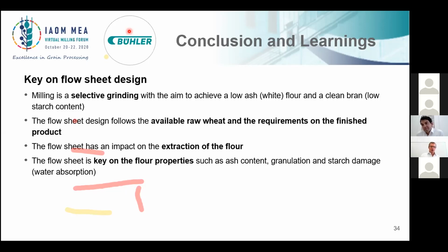There is more a relation between the design of the flutes and the wheat to be ground. So let's say if we start on a hard wheat, we go on more dull flutes. So first break, second break definitely will be dull.